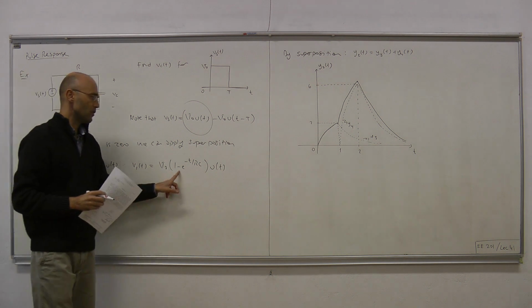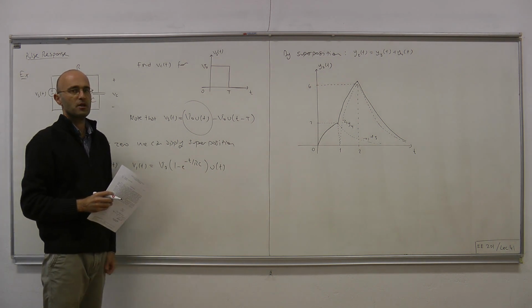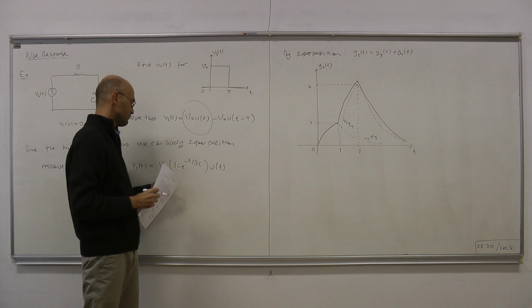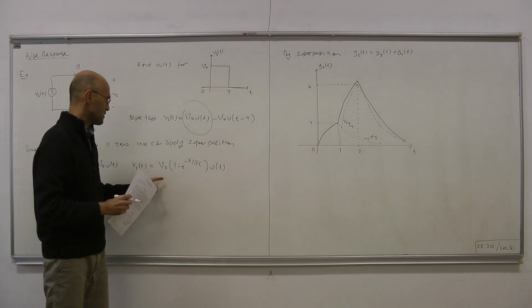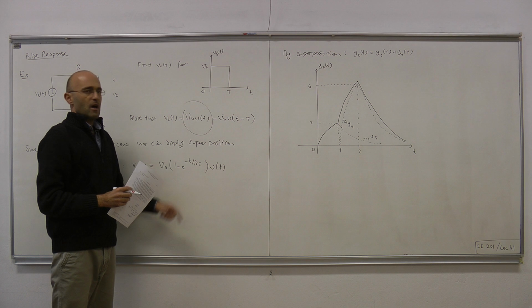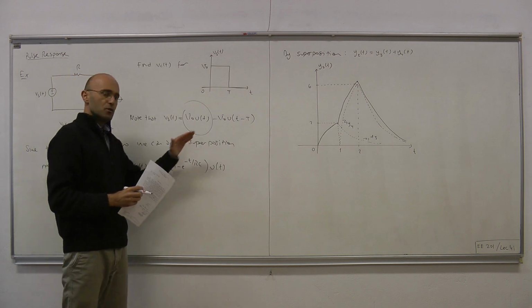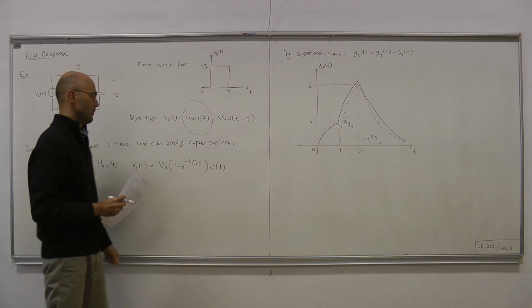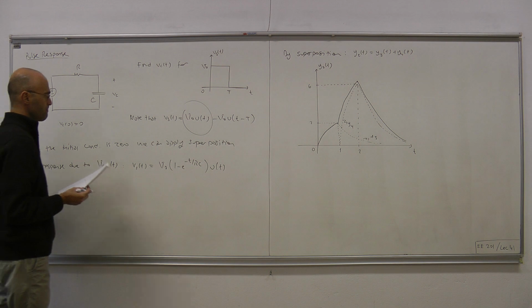Okay, it starts from 0 because at t equals 0, 1 minus 1 is 0. And what happens is it converges with the time constant of RC to the constant value of V0. Okay, so that's the step response.